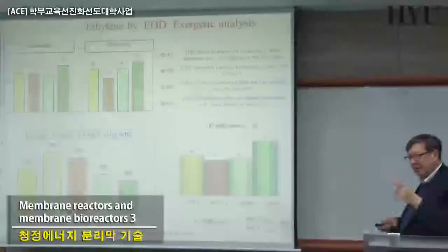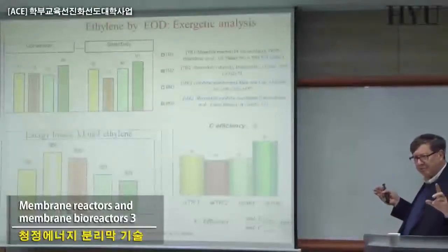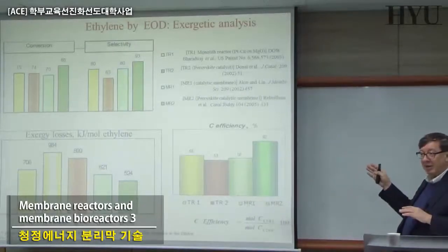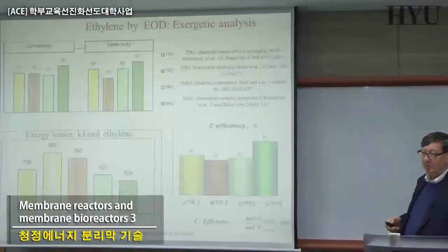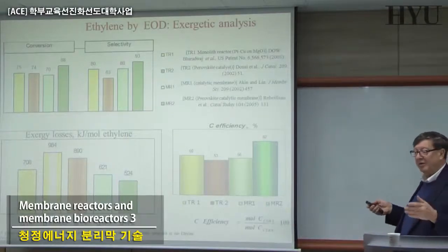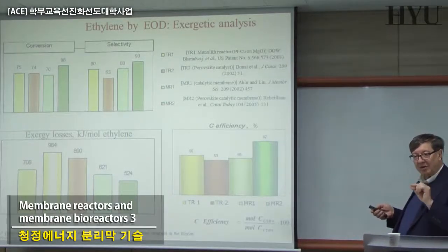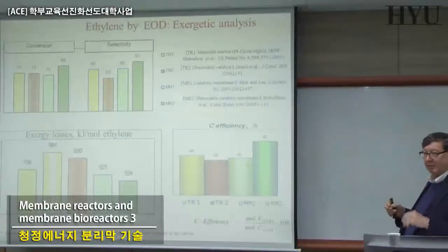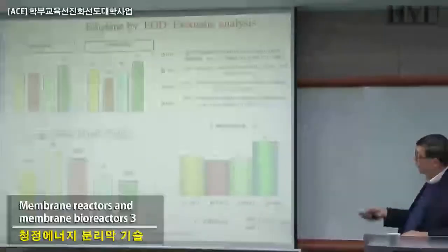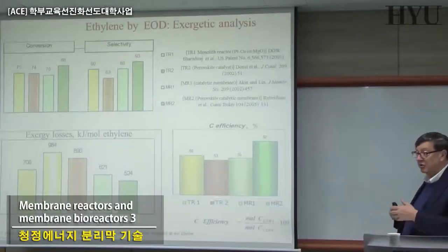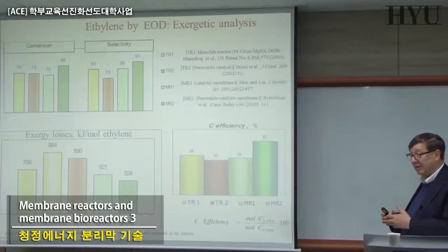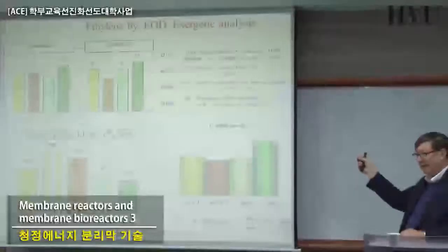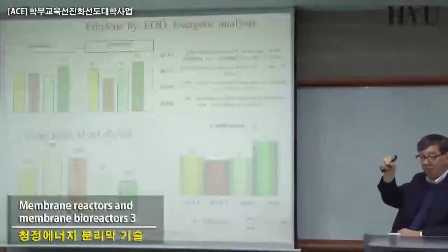Remember that perovskite is a very special kind of system. They are crystalline materials, and there is no selective diffusivity mechanism here. There is no Donnan effect here. Everything is related to the number of defects present in the crystalline structure. When there are oxygen vacancies, for example, these perovskites are a mixture of metal oxides, and oxygen from the air is activated at the surface, jumps into one vacancy, and moves to another one.